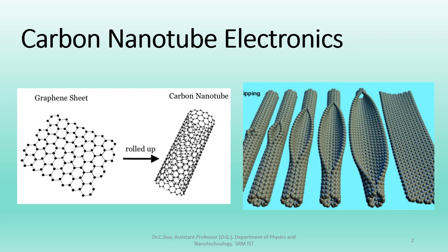Recent progress shows that CNT transistors can be made without doping by controlling the contact between the metal and the nanotube. This allows CNT FETs to keep their perfect atomic lattice and potentially outperform modern silicon devices.